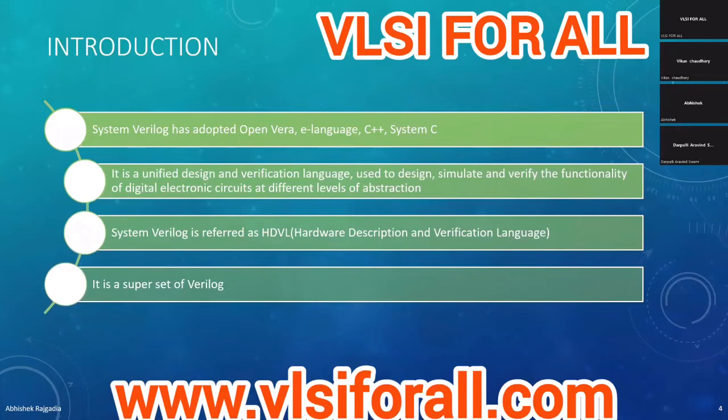If you have coded a scenario or a part of the testbench at the level of the audio IP, that probably can be reused at the SoC level, because verification is no longer limited to one level. The same feature is verified at different levels, like at the SoC level, the subsystem level, the IP level, and the sub-IP level also.